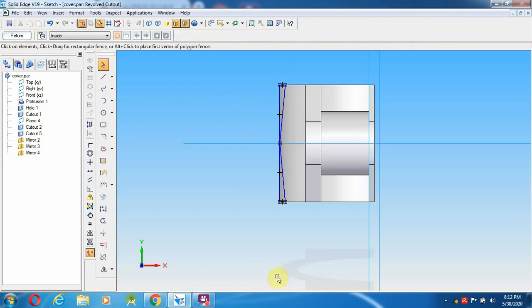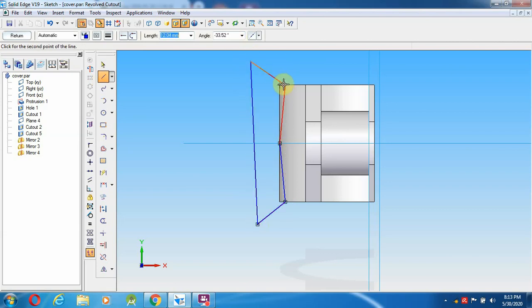Okay, now select the trim option, this as well as this one I'm going to trim. This I drew for reference purposes. After drawing this, select a line from here to make it the profile, like any profile, it's not an issue, since it is the cutout.